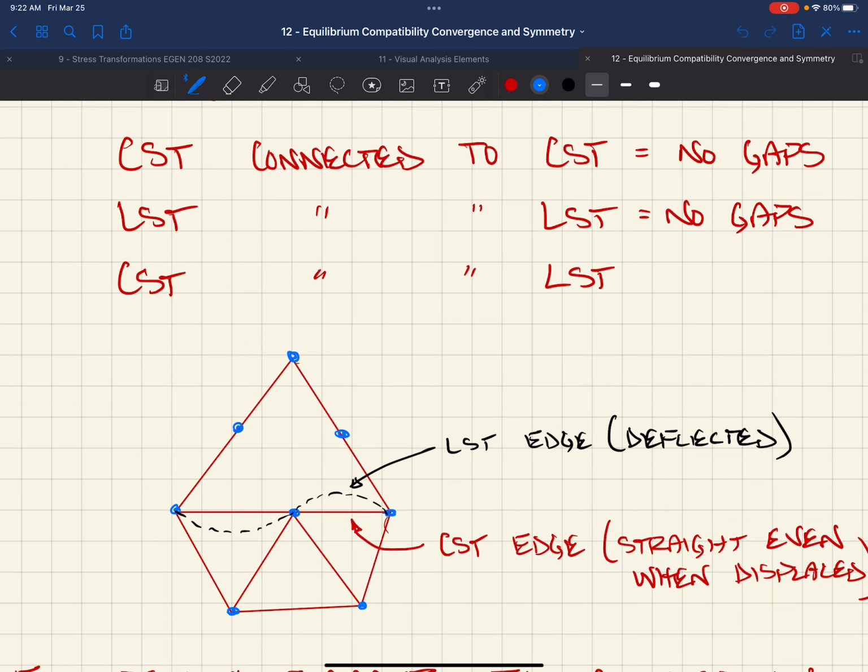Oh, like you're saying you have that constant stress in each element, but if you have a linear strain triangle, wouldn't you have linear changes in stress, and then you could have compatibility? You might, yes. You could, yes. Because you would have the ability, you wouldn't have the jump. Yeah. You wouldn't have the jump.